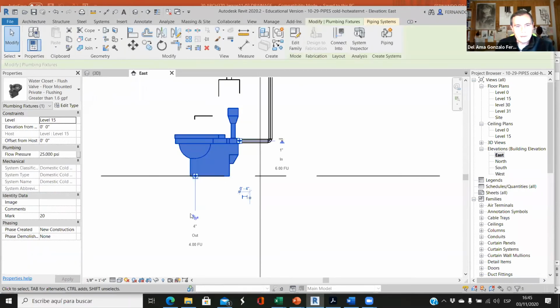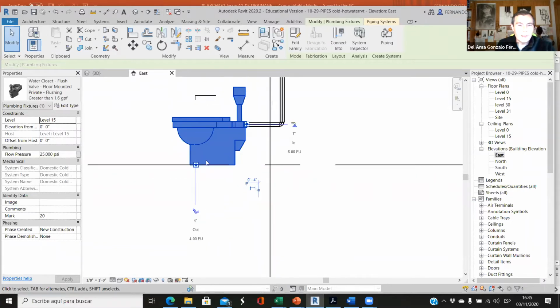So if we select the toilet, you see that here we have this create pipe. Okay, so there are different points here. This is for the plumbing system, and this is for the drainage. And here we even have the fixture units. Designing this system is about fixture units again. So we have the water supply fixture units for the water supply system, and drainage fixture units for the drainage system. But now we are familiar with this concept of fixture units, so we have the same with this.